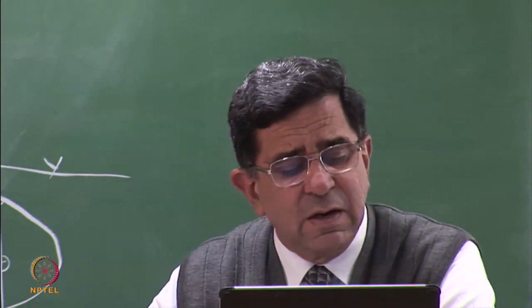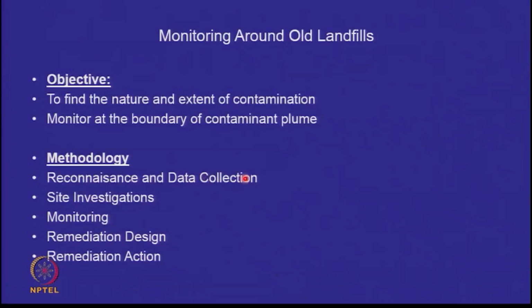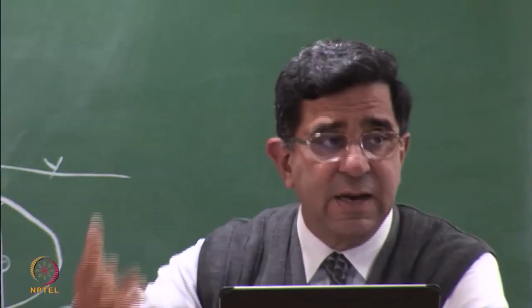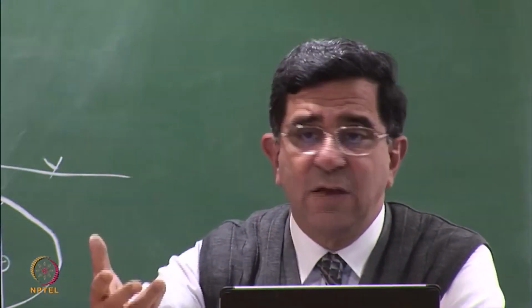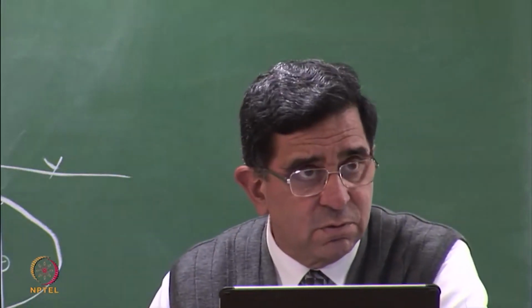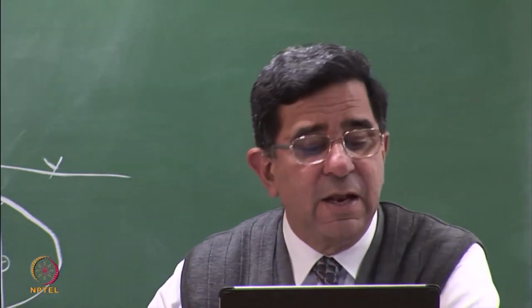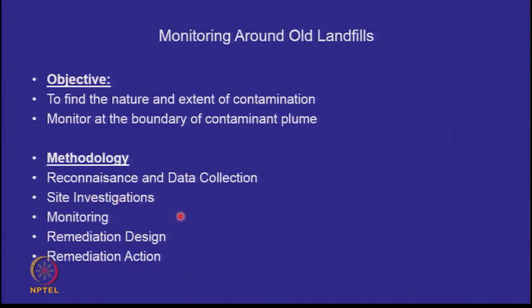So typically we will do reconnaissance and data collection. If there are some tube wells already there, or some hand pumps in that area, you will go and pick up samples from all those areas because they're a natural source of information for you. You don't have to drill holes. Then you will conduct site investigations. And after you have conducted the site investigation, you will do monitoring. That means set up your monitoring regime, and then you will do a remediation design.